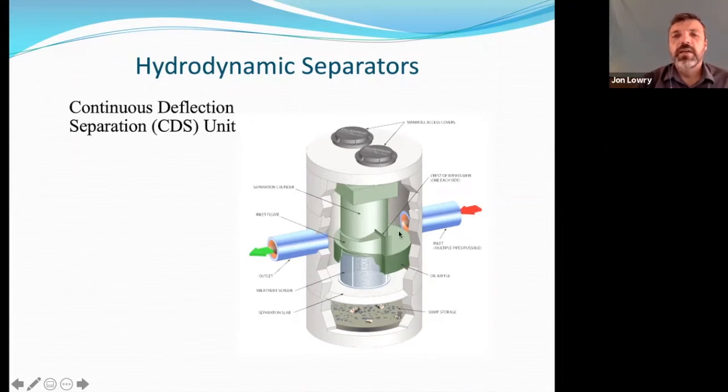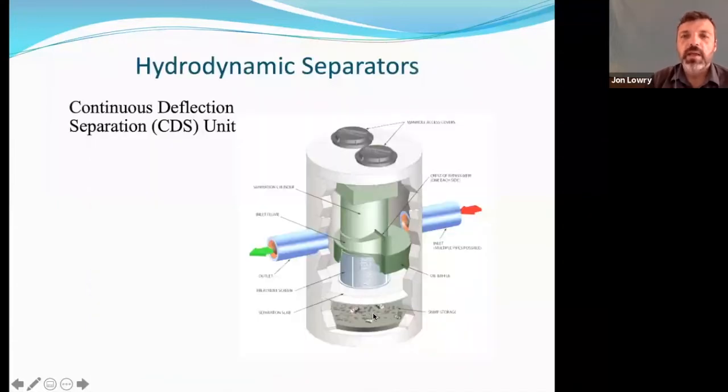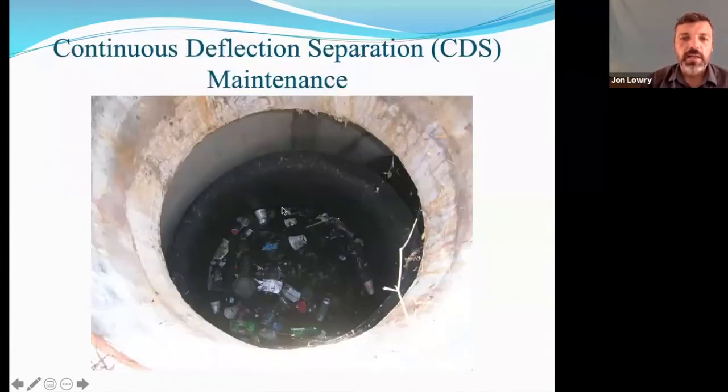As water flows in, they're actually designed during flow events to create a swirling action, and the swirling action causes the fine sediments to basically go into the middle of the whirlpool, and then they settle out into the settling chamber down here at the bottom. And floatables get trapped underneath this baffle system, and those can be cleaned by just popping the lid and skimming the floatables off the top.